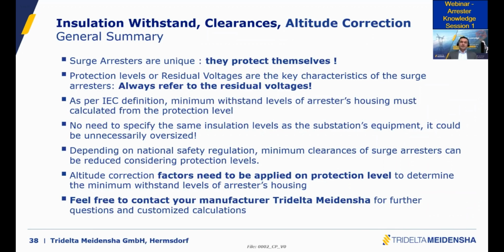Always remember that surge arrestors are unique because they have a self-protecting nature thanks to the metal oxide varistors, the zinc oxide. Those protection levels, those residual voltages, which are coming from the non-linear characteristic of the metal oxides, are the key characteristic of the surge arrestors. So it makes sense that we are using the full potential of the arrestor when we make a substation or transmission line design.